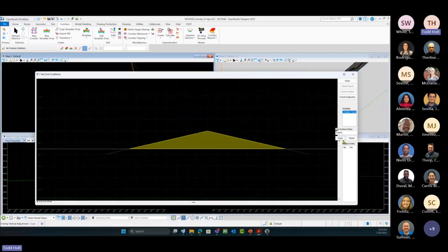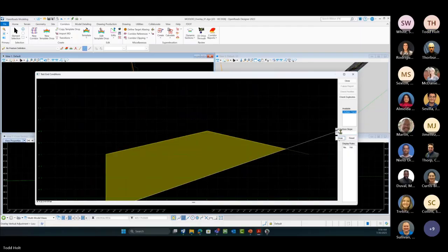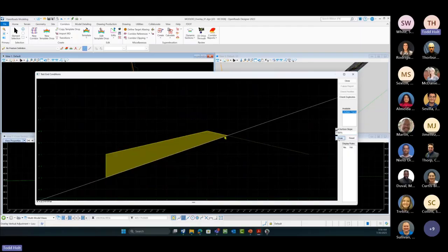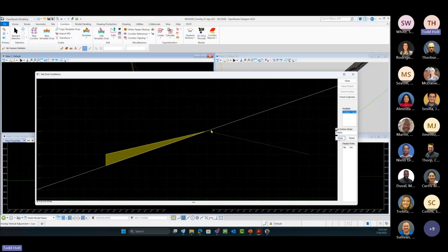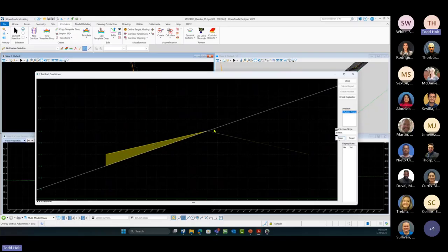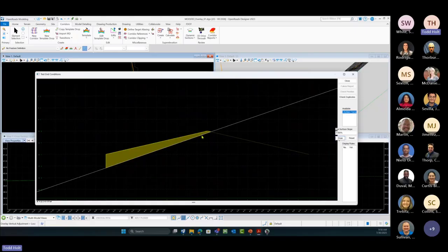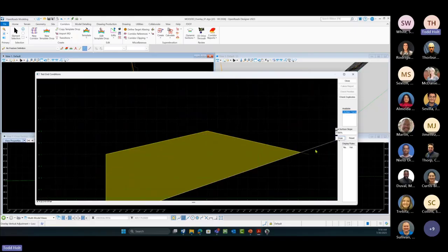the surface. If, say, we put in, we'll mimic just a 3% slope for our existing surface, and then we can draw that. So we can test that out to see what it's doing. So anywhere that this is going to get above the existing ground, we need to create an overlay or an overbuild on that component. Right? But if we get above that component, it's not going to draw. But if we get below it, we'd have to overlay to meet that pavement design from that existing ground.